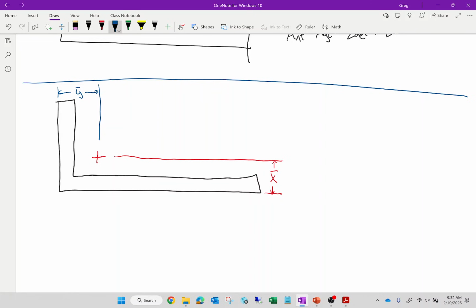By the way, which r value do you use for slenderness for an angle? r min, which for an angle is r z, the Z-axis, right? Angles do not exhibit symmetry about the X or Y axis, which is why there is an r z to begin with. Anytime there is a shape in the manual that doesn't exhibit symmetry with respect to either the X or the Y axis, there is a principal axis. Now, how do they figure out that principal axis? They break out a little thing called Mohr's circle. Remember that?